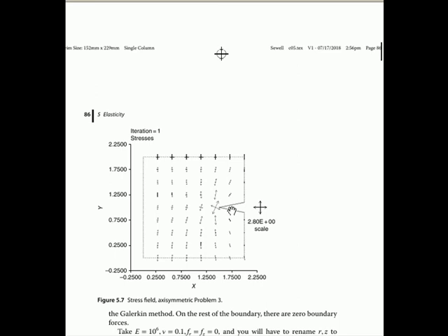There are some forces at the top, and that's causing large stresses at the notch. Anyway, axisymmetry can sometimes be used to reduce down to a two-dimensional problem, and in that case it's much, much simpler. In fact, you can even use the Galerkin method for it now, which is what's done.